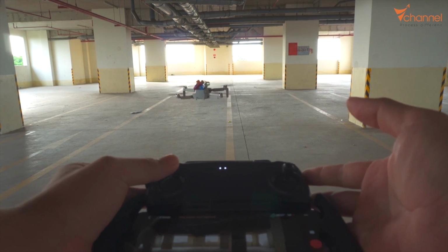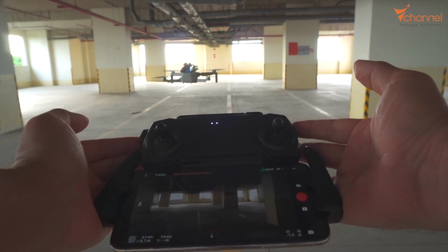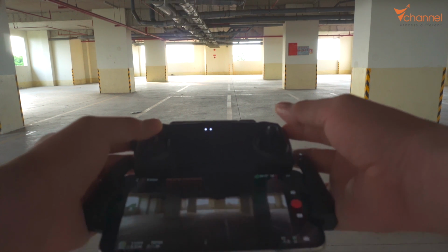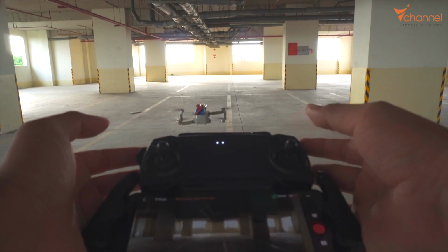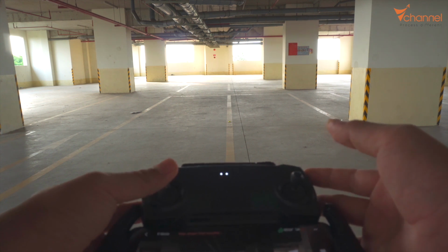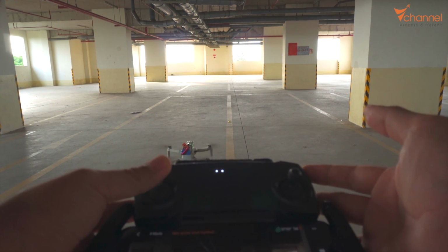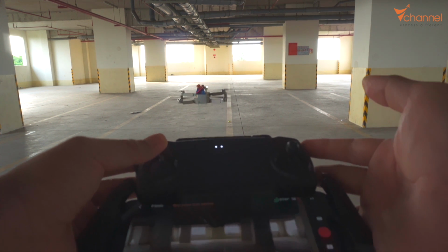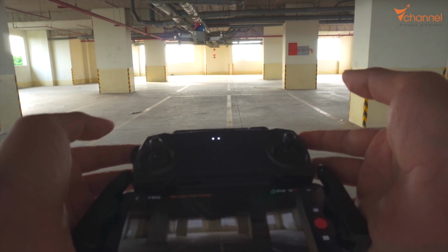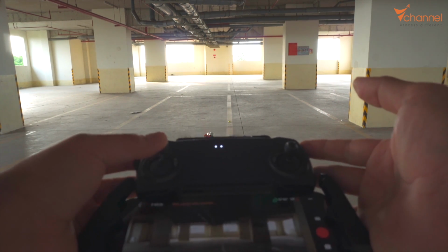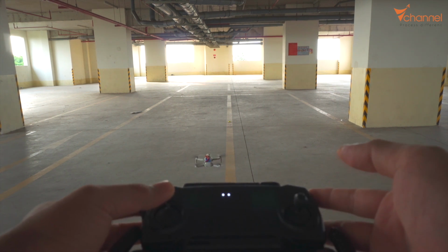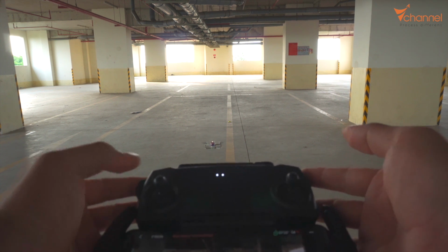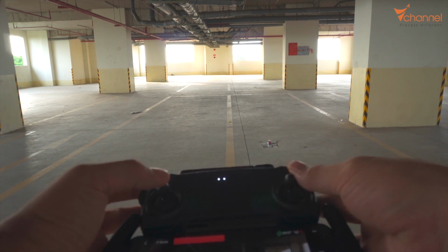As can be seen, when I release the joystick, the aircraft decreases its height automatically and is very difficult to control, even out of control. In this situation, there is no wind, so it's very dangerous when we fly in a real environment. Because right at that time, it has no superfluous power to fight against difficult conditions such as wind. The power must be used for the motors to carry the new battery. So we must modify in order to add weight lower than 171. If we modify higher, it will affect the safety of flying.